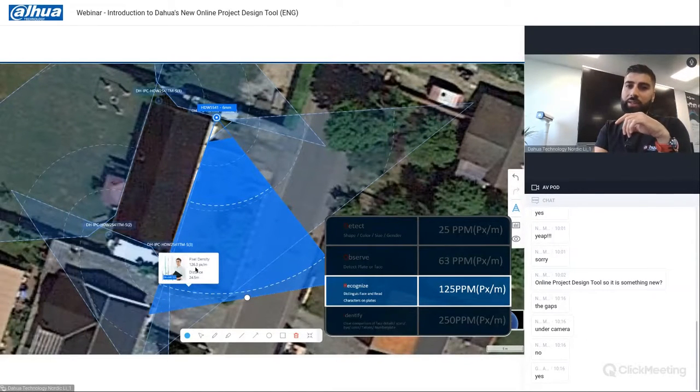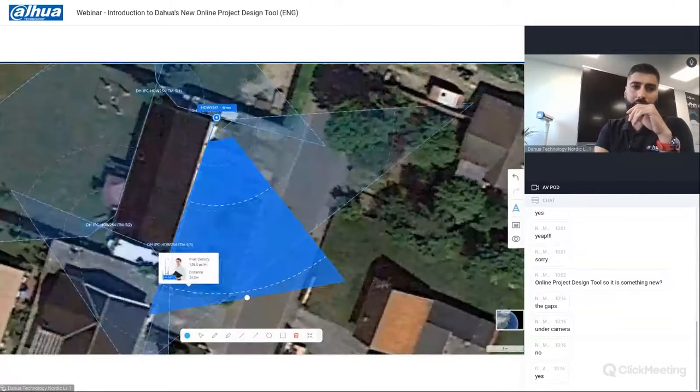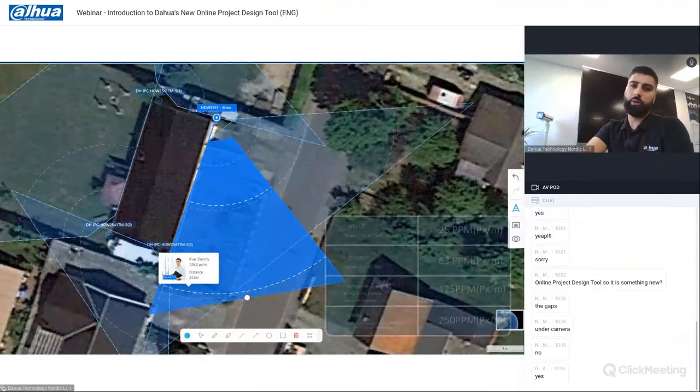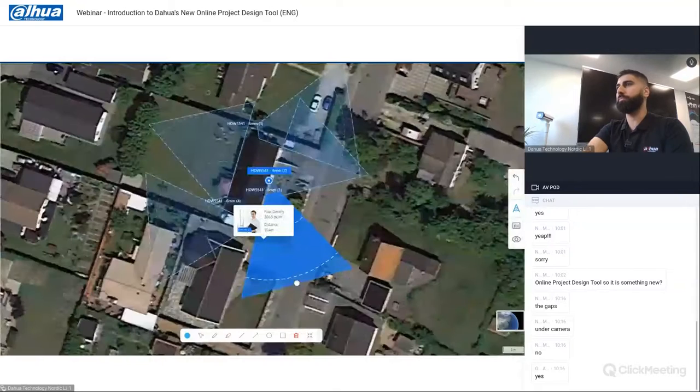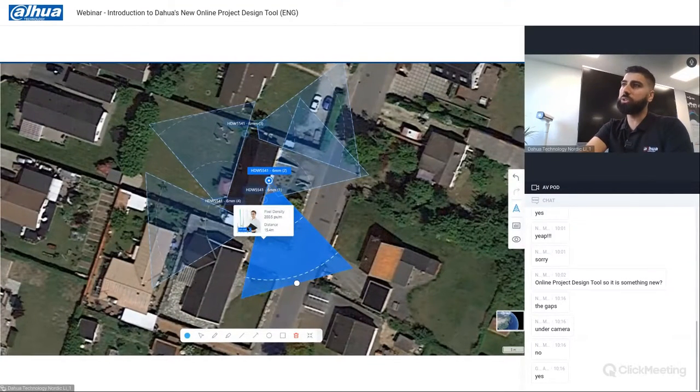Another way of designing it is you could use varifocal cameras. They would be a little bit more expensive, but it would give us even better coverage, or we can adjust the angles as well. Apart from that, if we exchange all the cameras to 5 series, we get the AccuPic feature as well, and we get better coverage because of the lens. The 2541 does not come in a 6 millimeter lens option. So just by adding one more camera, I get complete coverage of the front surface of the whole area, which is the most important part.